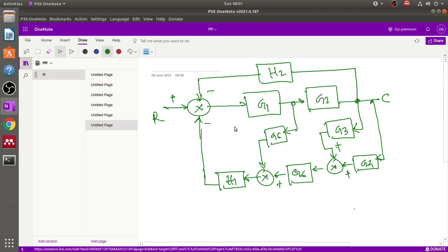Yes, right. Now this is again G5. Now solve this problem. So this is a very complex, you see that, but it is very easy. First of all, in the right hand side, we see that this G3 and G4 are basically coming from the output, but these two signals are just in the parallel rule. So therefore we add these two signals. Okay, this is our first task.